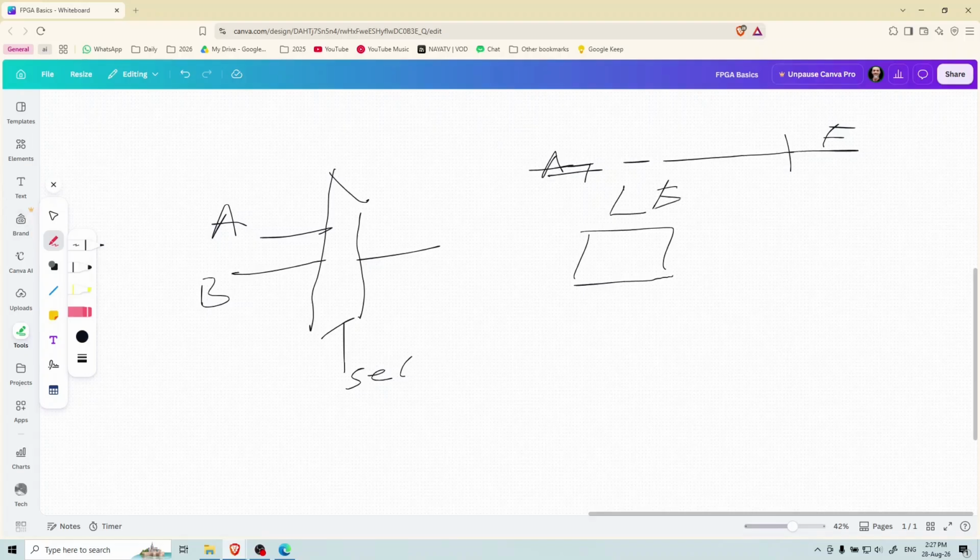You can call it a logic element. Okay, or it has a big multiplexer, or in terms of FPGAs, it's called a LUT, lookup table. Lookup table is the same as a truth table, so it can be used to implement any function. And then you have a memory unit, which is a flip-flop. If you have studied digital logic, you would know what a flip-flop is. So basically, a logic element is a LUT plus a flip-flop. This is the simplest form of a logic element. More advanced logic elements have some other features as well, but we're not going to go into that.